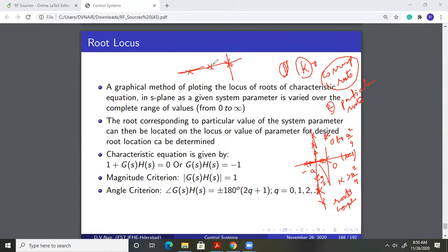So when you have three open loop poles, you may see that in the corresponding root locus, these two branches start progressing towards each other with increase in gain k. Each starts at k equal to 0. So here the root locus will develop something like this. The branch that is generating at this open loop pole will move in this direction.